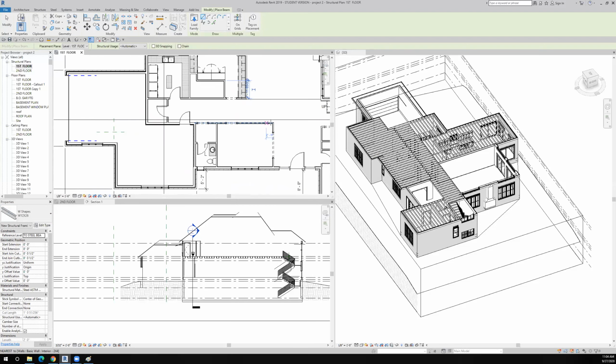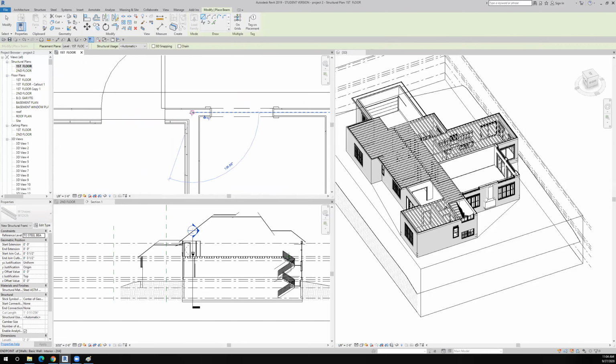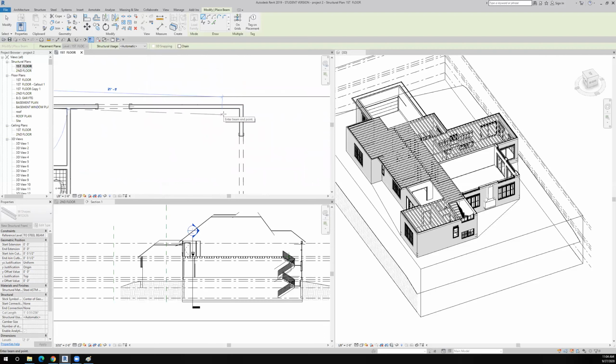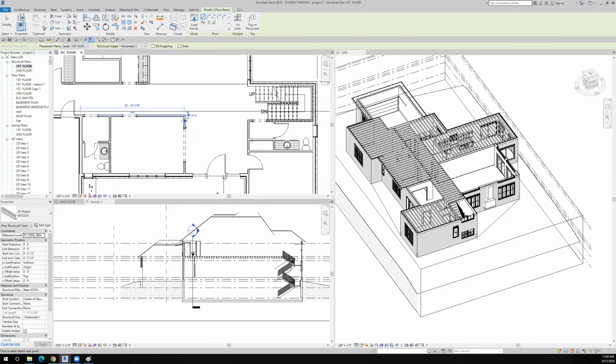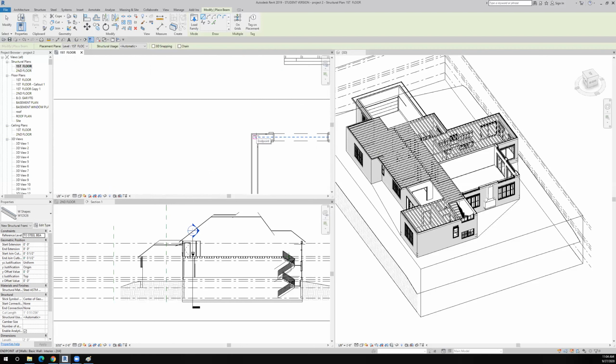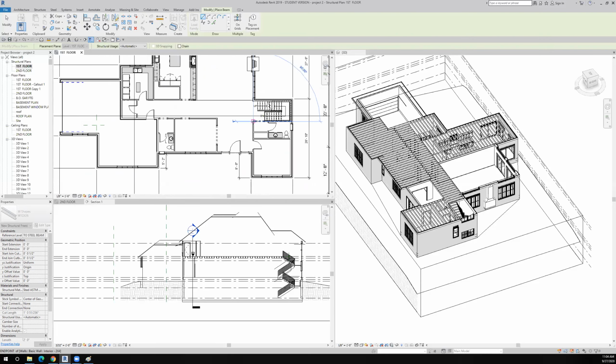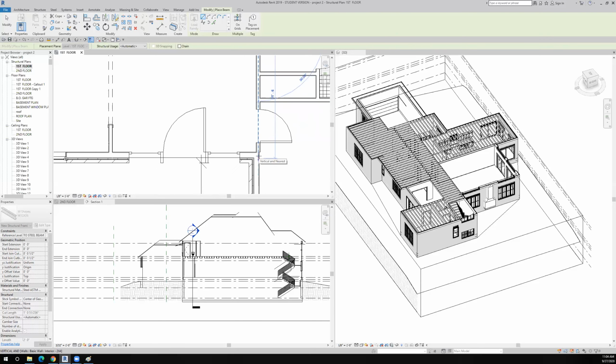All right, let's see now. We want to go over here because that's a bearing wall as well. This happens to be the basement wall across here, so that steel beam will start here at the center line of that wall and go over to here. Okay, can't see it, that's all right. And now this is a bearing wall, this is outside wall, so that we don't need a steel beam underneath it, but here we do. So I'm going to put that steel beam in from here all the way over to there.